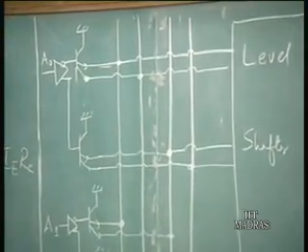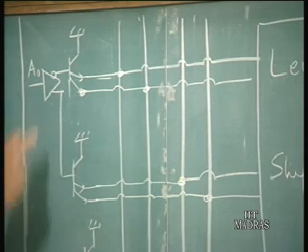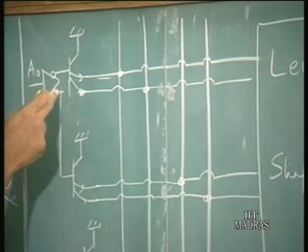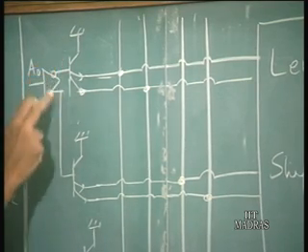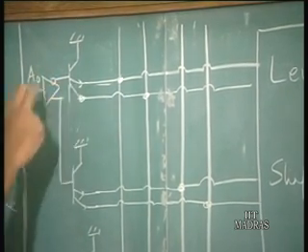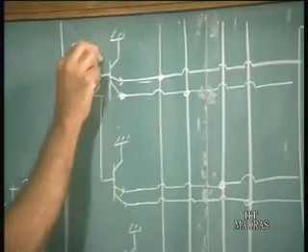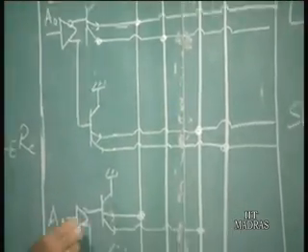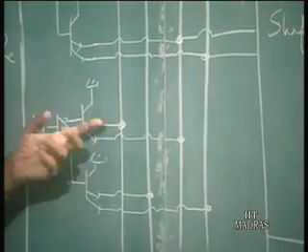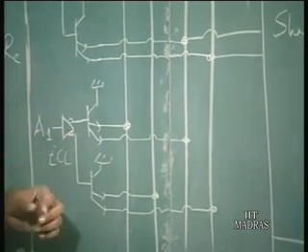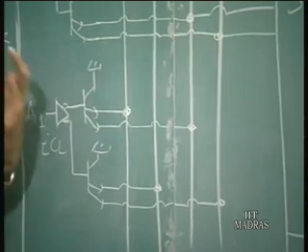You know that with ECL gates you can have the same output as well as the complement. So basically this is a NOT, and you get at the output A naught as well as A naught bar. And this is basically the emitter follower at the output of the ECL inverter. So these are ECL gates here, and this is the emitter follower at the output of the ECL gates. Now, because you have emitter followers at the output of the ECL gates, you can do a wired operation. So you can get logic by doing the wired operation.